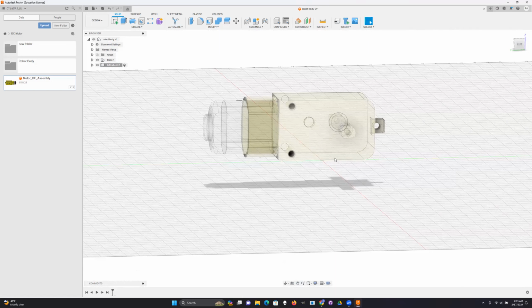I'm going to click on this. So when you are working with the component and you want to create the sketch to create your solid, you want to click on one of the faces. So it's the XYZ axis. You see here it says origin. Now you see the little XYZ plane in the middle of that. So that's pretty much what you just need to do.